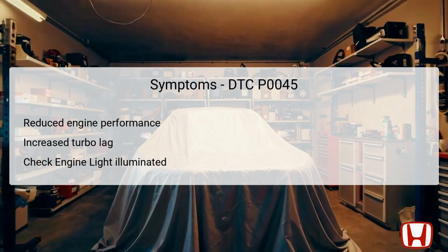When the DTC P0045 is active, drivers often notice several signs that indicate a malfunction within the turbocharging system. The most common symptom is a noticeable reduction in engine performance. The vehicle may feel sluggish or less responsive than usual. This reduction often correlates with increased turbo lag, which means there may be a delay in power delivery when accelerating.